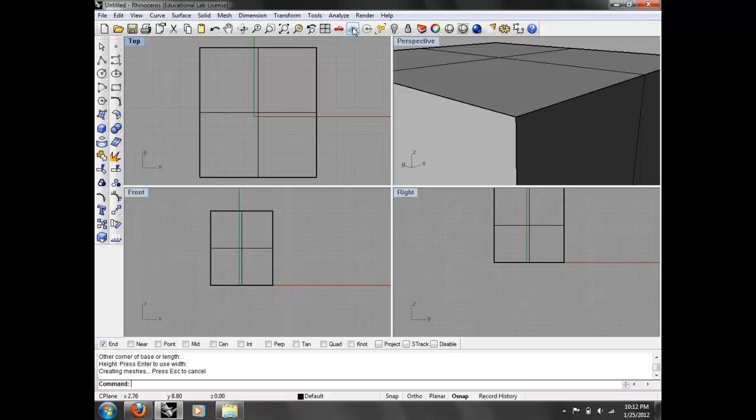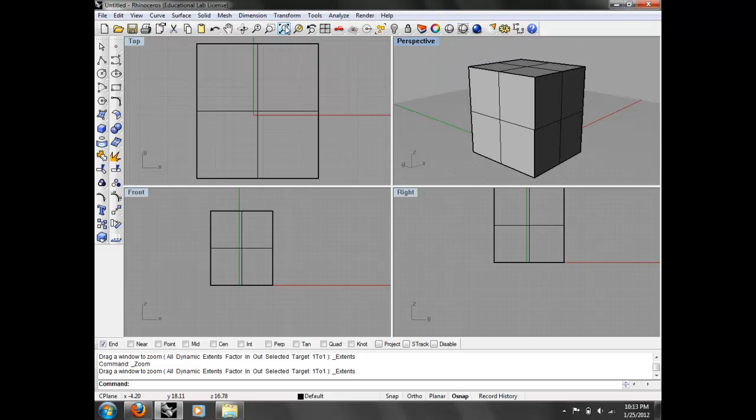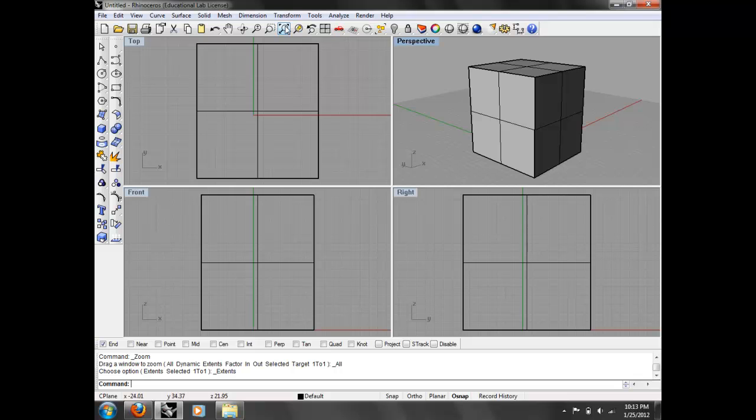There's other controls up here. You'll notice when I mouse over some icons, there's a tooltip that has the left mouse button, and then there's one that says the right mouse button. You see where the icon turns dark over the mouse. So if I single click, then I get zoom extents, which fills the viewport with all of the objects. You guys know this from AutoCAD, probably. If I right click, it's going to zoom all the viewports instantly. Okay, so that's a handy thing to know how to do.